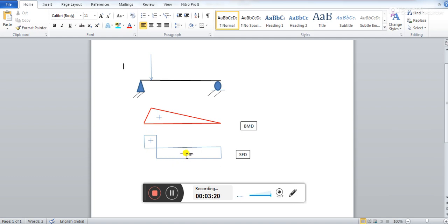And you observe one thing here: when this load is put over here, that means it is a fixed load, a static kind of load, and when the load is put at this position on the beam, the shape of the bending moment diagram will always be triangular like this, and the peak of the triangle will be just below the load.